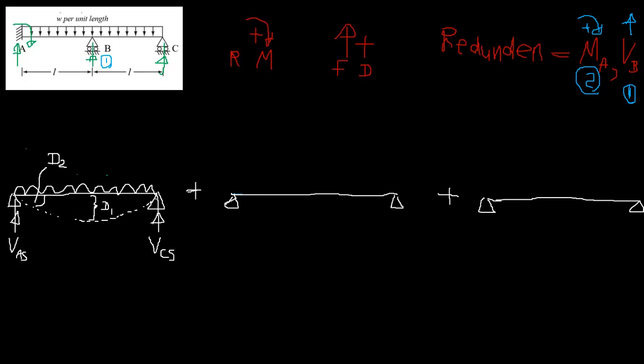So now this is the shape at B, and this is the rotation, because the moments are corresponding to the rotation, right? You remove the restraint fixed clamp, so it can rotate. So it will rotate T2, right? So now it is not the original structure. So what you are going to do is you remove the force and you apply one at a time, right? You remove the force first and then the moment, and you are going to apply a unit force here.